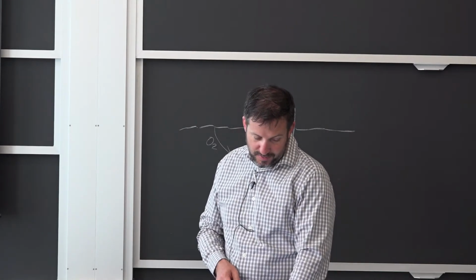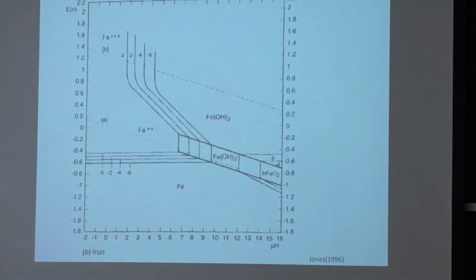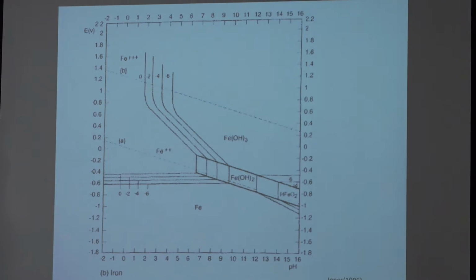Okay, now what are we going to do? For steel, one easy thing to do is to move into a region of stability of the oxide. I'm only going to mention the one that I'm most familiar with, which is putting the steel in concrete. So you raise the pH, and then all of a sudden the oxide that you form on the surface of the steel is stable. It becomes a little bit like aluminum. So it's self-protected. Now, there are other ways to reach that level of protection.